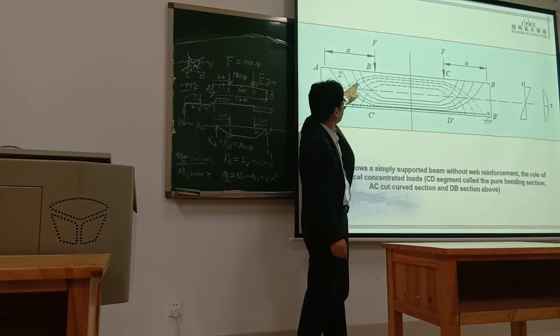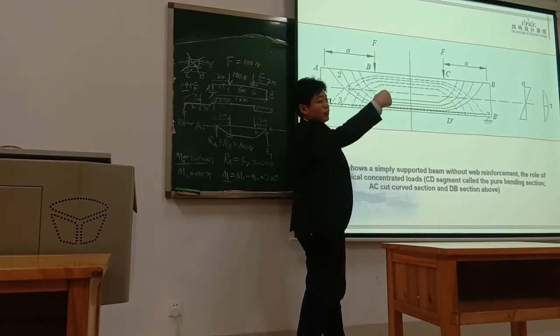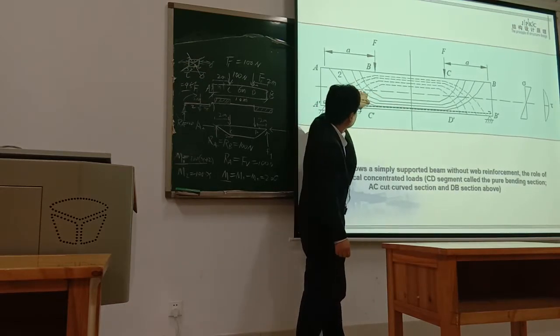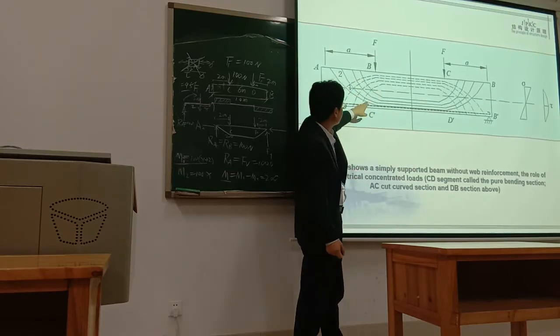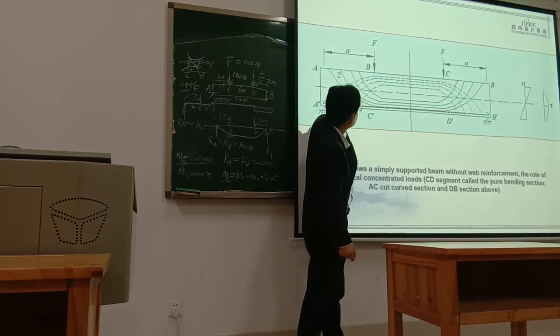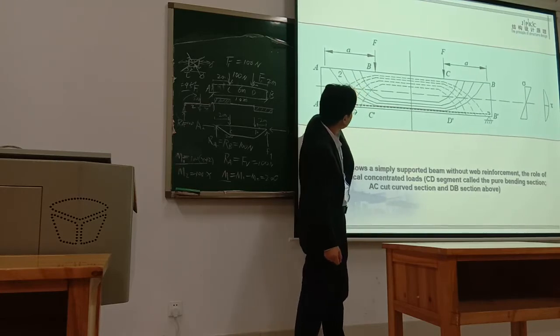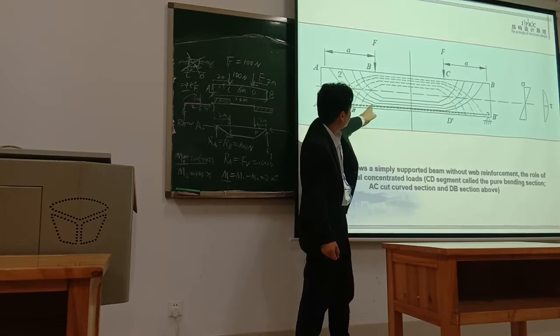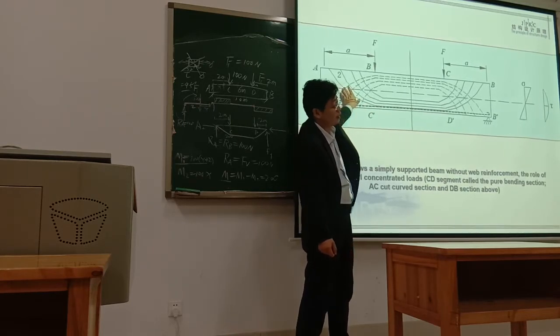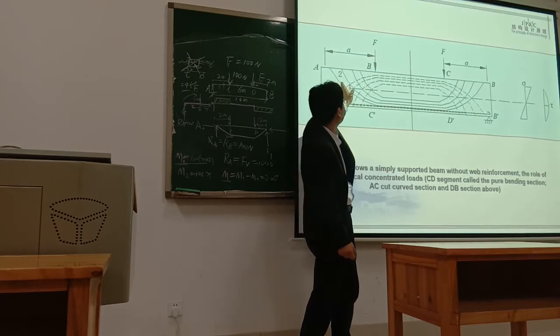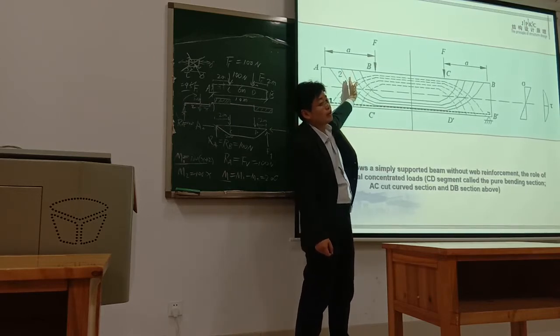So this is the compression direction. This line is the principal tension stress. So the principal tension stress is along this direction. Near the middle it's merely 45 degrees, but from here it greatly increases. Now at this position it's nearly 45. Of course, going up, it becomes larger.